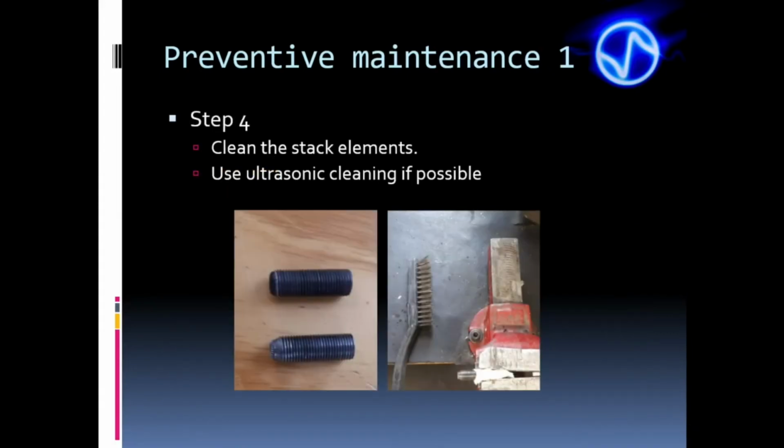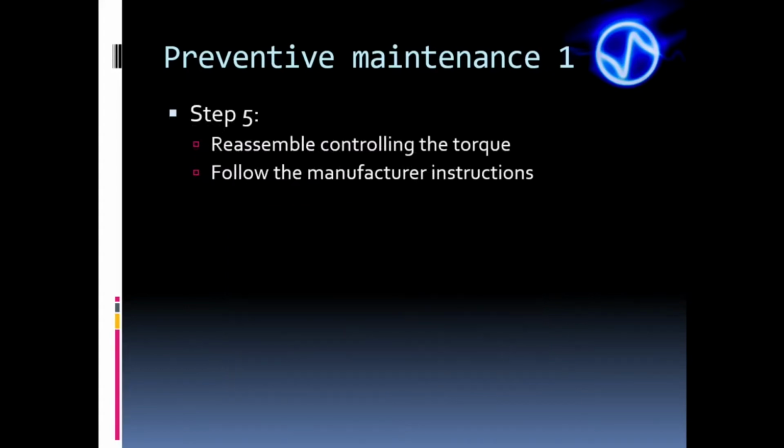As well as restoring the interfaces, it's necessary to inspect studs, threads, and everything else to find and restore or replace damaged parts. Although not mandatory, it's advisable to use an ultrasonic cleaner to clean these parts, as it also cleans hard-to-access regions as threads and holes. Later on this course, we'll learn about the recommended tools for these procedures. Once all the elements of the acoustic stack have been restored and cleaned, we need to reassemble it.